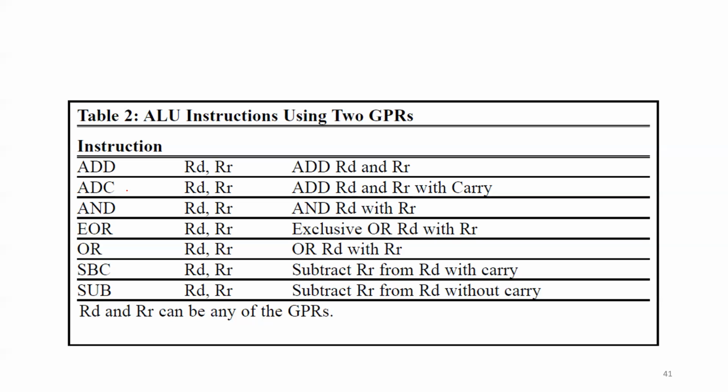How can we solve that? We have many techniques. We can, for instance, divide the 16-bit data into 2 registers and add in 2 registers instead of 1 register. Later we can see some examples on that. However, for now, what's the advantage of add with carry? Add with carry is going to let you know that if the carry flag is active high, your result is incorrect. So this is just a flag. It's not going to solve the issue, but it will just let you know that you have an issue in your program. Okay, so this is called add with carry.